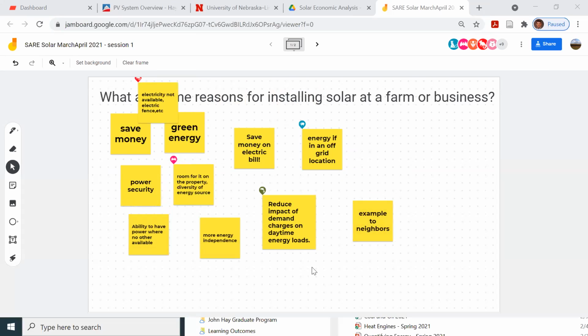And we actually have a hog barn here in Ohio that we have some advanced energy meters installed on, and they have a 12 kW PV solar system installed on the rooftop. We're collecting data points every 5 minutes, and they're on a demand rate. One of the things we've noticed as we look at the load profile is the hogs are active, typically for a couple hours after their solar kicks off for the day, where you still see feed auger motors cycling on and off, well pump motors kicking on and off.